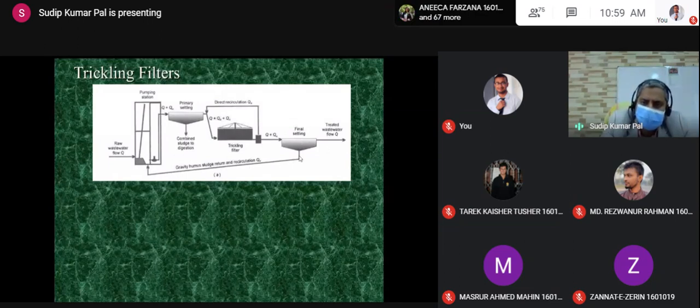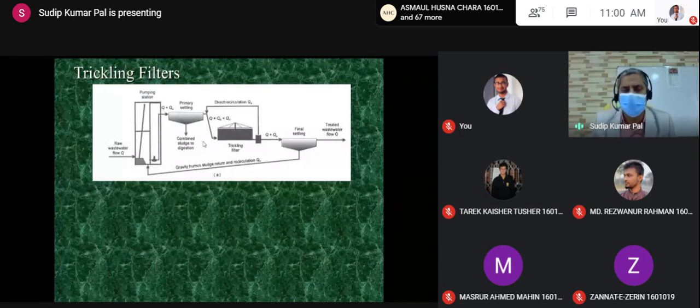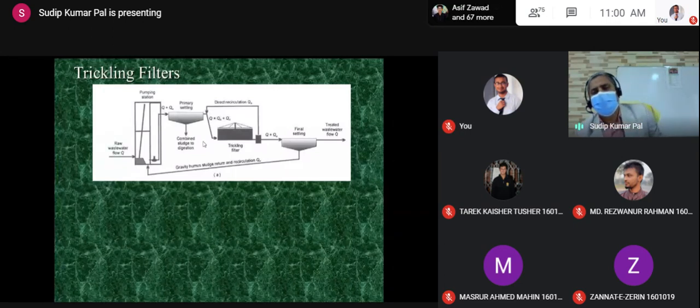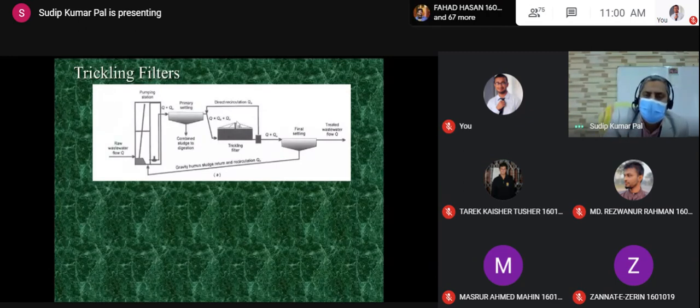So this is called a staging system. You can take some wastewater from the system and put it in again here. So it's just a kind of combined sludge to digestion. This means you feel the clarifier is still not very clear. So it depends on your system. If the flow rate is high and the organic loading is also high, it may not get enough time to degrade completely. In that case, sometimes we allow return flow. So this is also available.